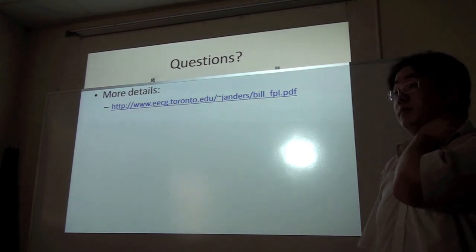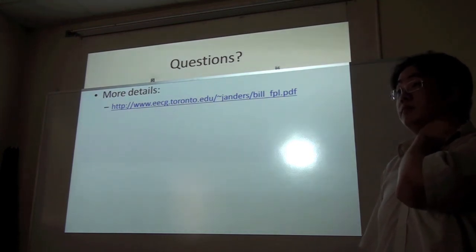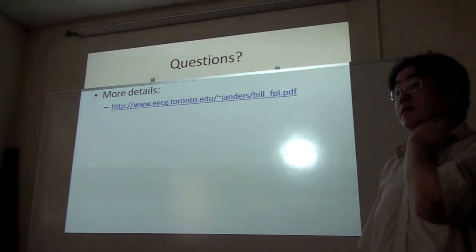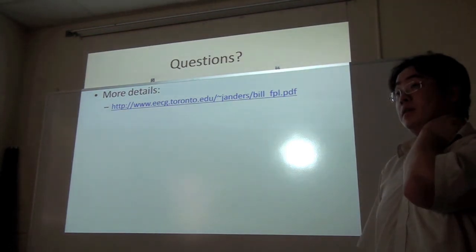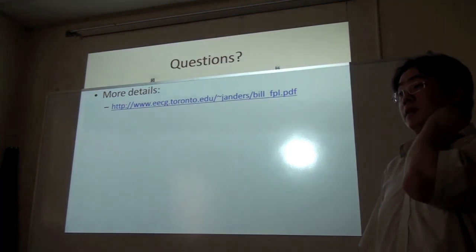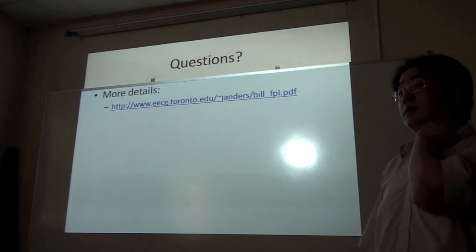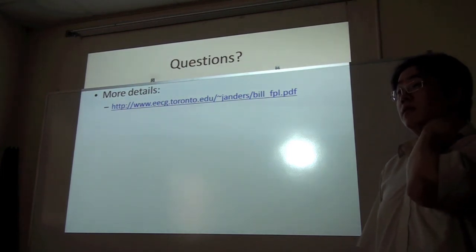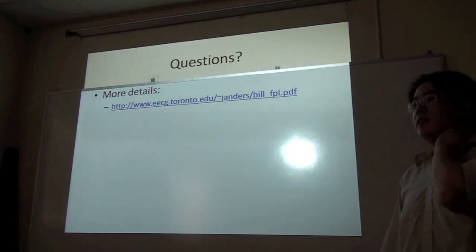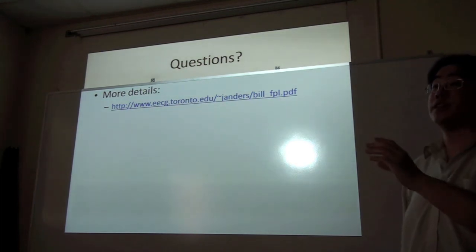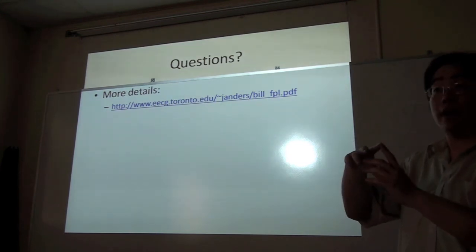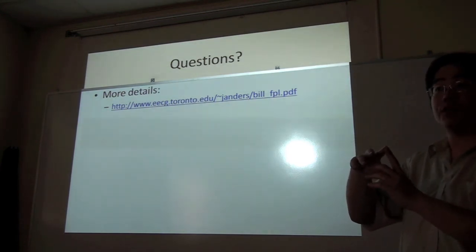and route the design, you can selectively target flip-flops and turn them into latches. Right. That's actually not true, because within a CLB, you can't select individual flip-flops and turn them into latches. The other thing to keep in mind is that from Virtex-6 onwards, only half of the flip-flops can be turned into latches, the rest can only stay as flip-flops. Okay, I did not know that, but that's interesting. So basically, inside one CLB, you can only turn at most half of them into latches. Is that what you're trying to say?